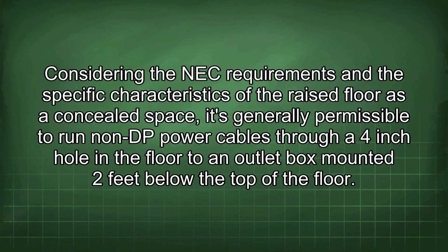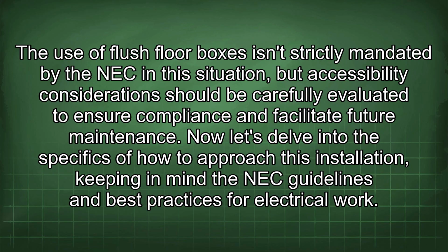Considering the NEC requirements and the specific characteristics of the raised floor as a concealed space, it's generally permissible to run non-DP power cables through a 4-inch hole in the floor to an outlet box mounted 2 feet below the top of the floor. The use of flush floor boxes isn't strictly mandated by the NEC in this situation, but accessibility considerations should be carefully evaluated to ensure compliance and facilitate future maintenance.